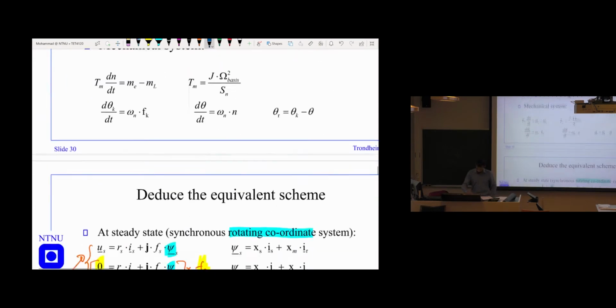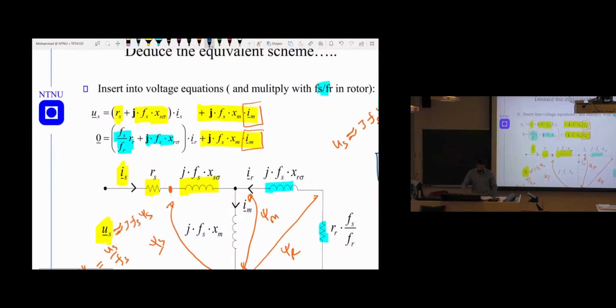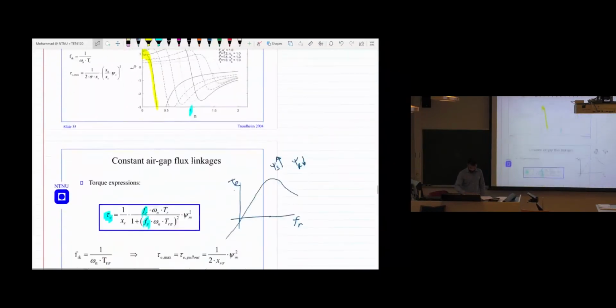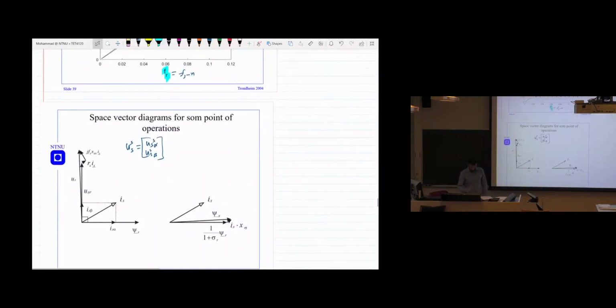So when we did the calculation there, we performed them in the phasor, in the circuit. It's also possible to do all of them in the matrix form, like the one that I wrote here. When you write in the matrix form, this means we have one alpha axis and one beta axis, or maybe one D axis and one Q axis. So when we develop the control, we usually write DQ. But in this course, we are talking about alpha K and beta K. So they are the same. We can do it like this.